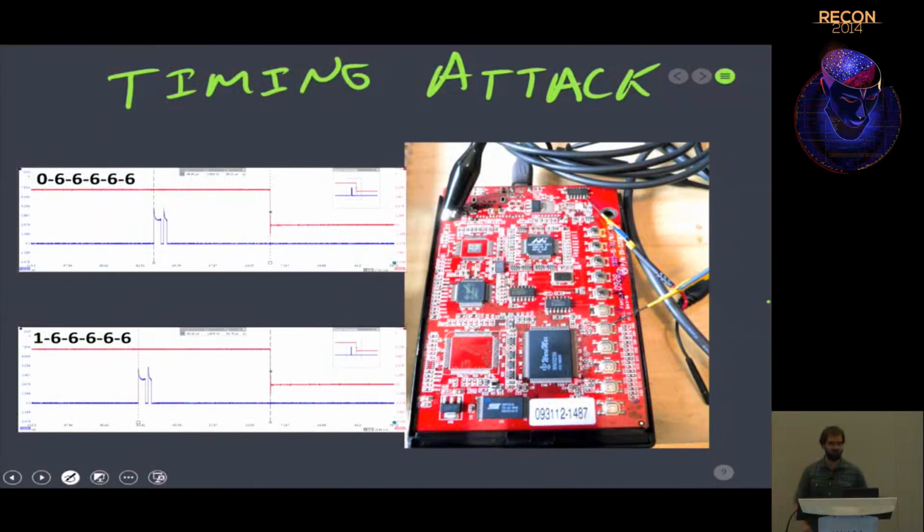So it's pretty cheesy. But how they do the pin check, and you'll see this in lots of stuff, is that you enter the 6 digits. After you enter the digits, it just has a while loop that's going through and comparing it. But you can see, and the theory is, there should be 1 million combinations of this password. So it's pretty secure. But the problem is, as soon as the while loop fails, it just exits. And you can see the amount of time it takes to do this comparison changing. So the correct password is 123456.